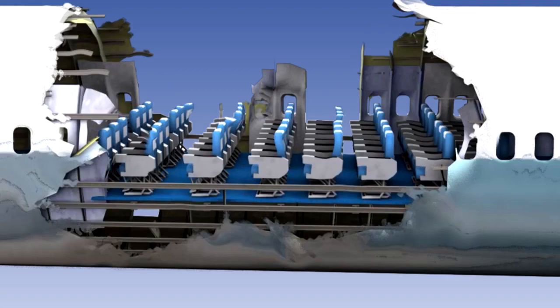Corrosion is the slow destruction of metal by electrochemical reaction. It is one of the most persistent defects found in aircraft. Rectification of advanced corrosion has been known to take thousands of man-hours. In fact, more than 10% of engineering downtime is spent in dealing with corrosion problems. It is therefore essential that it is recognized at the earliest possible stage, and that effective preventative measures are taken.